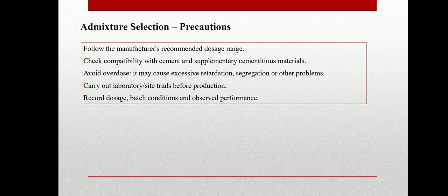This can lead to excessive retardation, segregation, or other defects that are hard to fix once the concrete is placed. Always carry out laboratory or site trials before going for full production. And finally, we have to keep good records: the dosage used, batching conditions, and the observed performance. So we can build a reliable knowledge base over